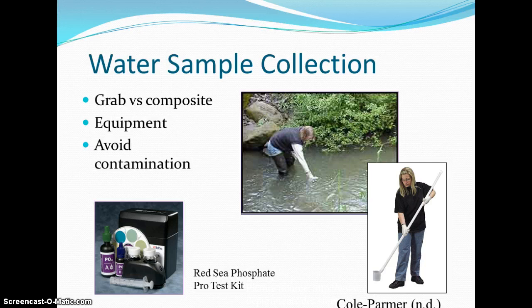In some cases, water samples may be collected for delivery to a laboratory for more sophisticated testing. The sample is generally preserved on ice, though other preservatives may also be used depending on the parameter of interest. For example, nutrients may be fixed with an acid solution to prevent changes between forms. As a general rule, most parameters should be measured within 24 to 48 hours, with few exceptions.